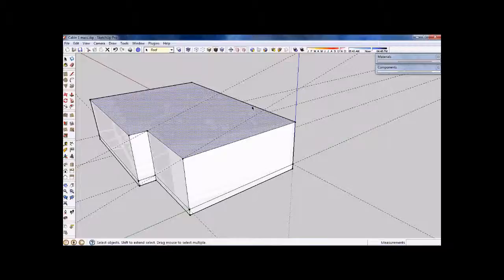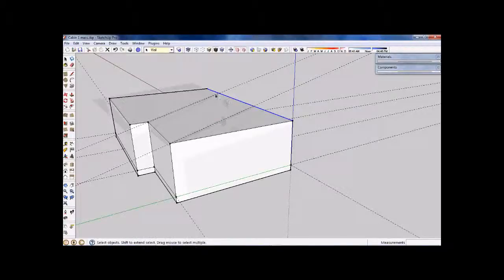There's no way I can simply move that edge at the moment in an upward blue axis direction and still create a coplanar face. I'd have to, at the same time I move that one up, move this in the same command. So SketchUp won't be able to cope with this line here moving at the moment, because it's glued to this ceiling.